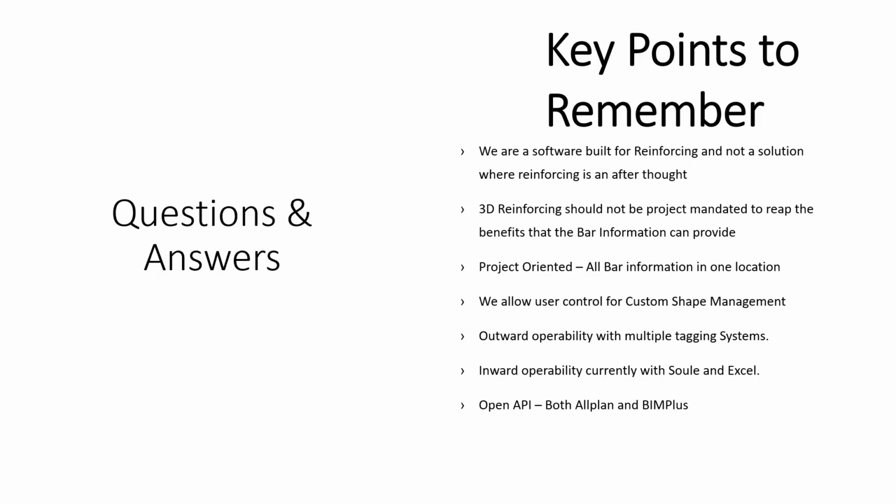But what we are working on is a way to track all the changes that were ever made. So right now, there's two things you can do to track changes. There's a little side note on why we'd want to bring something back. To track changes is when you export your file to BIM Plus, it always keeps the latest revision. So you can actually do a revision comparison from every time you bring in that file. So you'll very quickly see that if you change the bar from number 5 to number 6, we can track that within BIM Plus. As part of the next phase of our Rebar management software, we're going to have that tool built in.